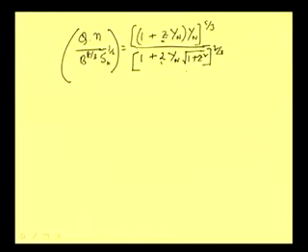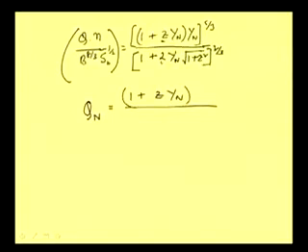But what about this part, that is Q·n by b to the power 8 by 3 and S_b to the power half? Let us check this. This we write normally as Q capital N, you can concentrate on the slide, and that is equal to 1 plus z into capital Y_n into Y_n to the power 5 by 3, 1 plus 2 into capital Y_n root over 1 plus z square, to the power 2 by 3.